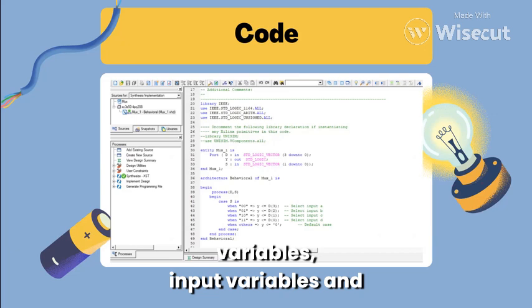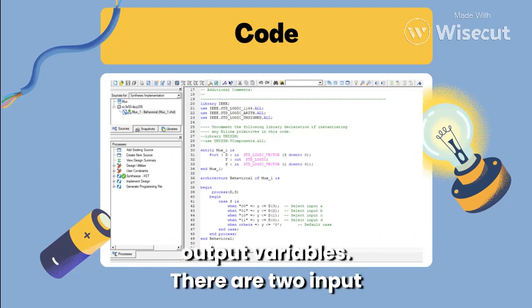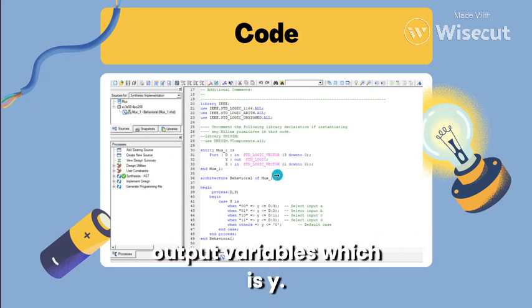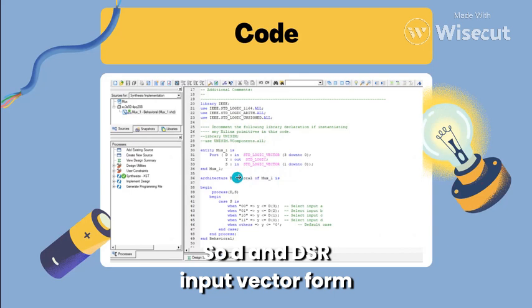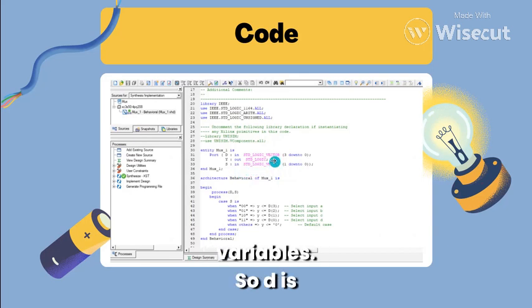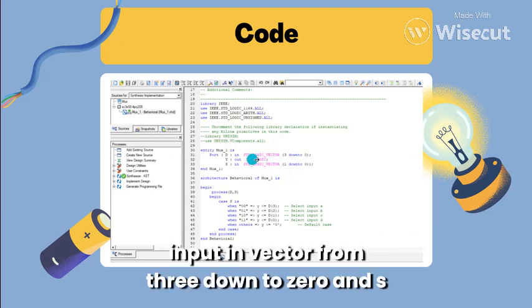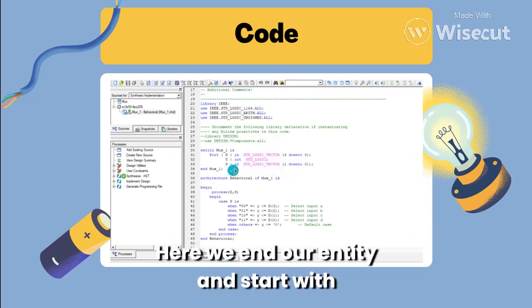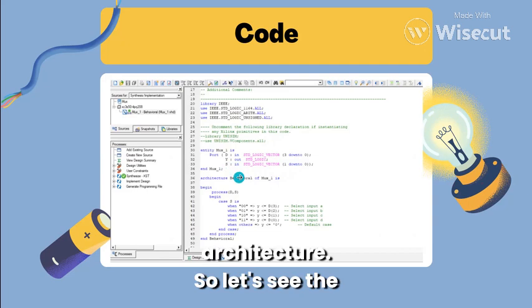In the port section we denote our variables, input variables and output variables. There are two input variables and a single output variable, which is y. So d and s are input variables in vector form. d is input in vector form 3 down to 0, and s is input in vector form 1 down to 0. Here we end our entity and start with the architecture.